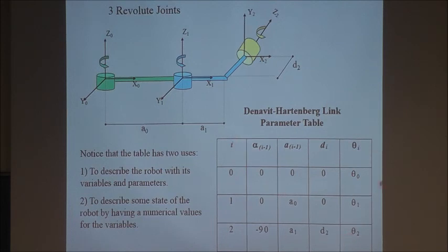Notice that in this table, some DH parameters are fixed, minus 90 degrees. I was telling you about that. Some are fixed. The rest of them are variable. So you move back and forth, you rotate here and there. That's the DH parameters. So this is the table I mentioned to you. It comes with your robot. This is just a simple example. It's nothing real about this robot example.